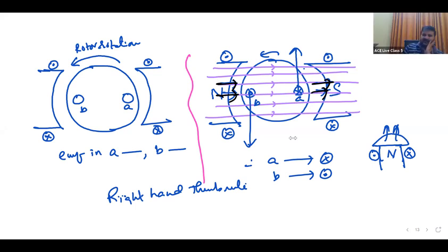The 4 cases. Case 1, when the conductor is rotating. What does the right hand rule say? Four fingers show flux, thumb shows motion of the conductor. When the conductor is rotating, no assumption is required because you can point your thumb in the direction of motion. If the conductor is rotating clockwise, you need to consider clockwise only; counterclockwise, the same.